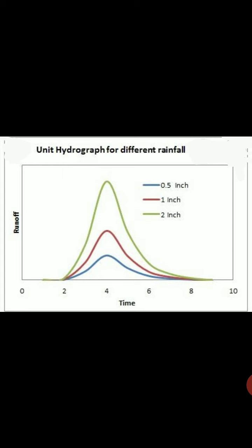What are the limitations? Limitations of unit hydrograph. First point is precipitation must be from rainfall only. Snow melt runoff cannot be satisfactorily represented by unit hydrograph.